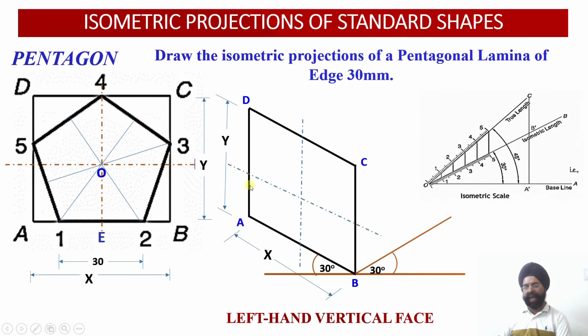So step number 1, the center point has been located. So measure the distance between A and E and A and F. You see, A and E, and this is my F point. So measure distance between AF or BF. Okay, so this gives me the center point. So once I obtain the center point, now next I need to locate all the 5 points.